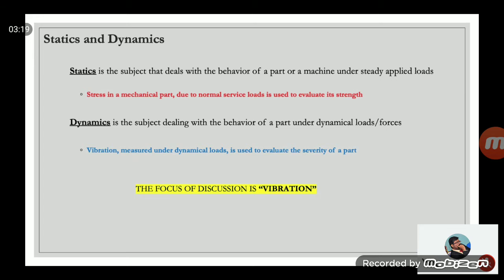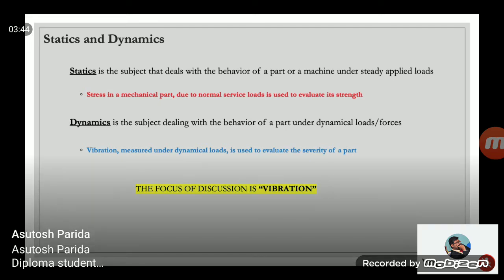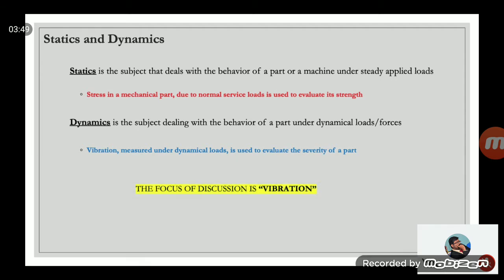If the machine is very close to the yield point, then eventually it can get to the yield point or ultimate at one point, and there is possible damage to your part. So the thumb rule is you have to be almost 50% away from the yield strength or ultimate strength. That's a guidance. That's all. Several situations may dictate that you have to increase that allowable limit, and then you can do it.